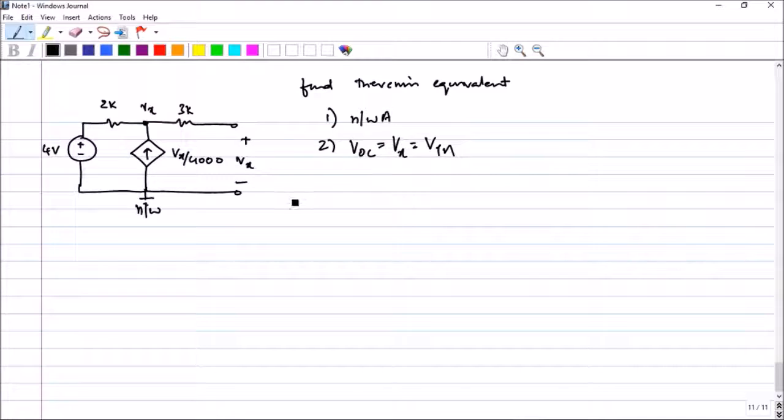Now let us go around and find the value of Vx. I can use node analysis here. So Vx minus 4 divided by 2. Now I always put 2 because this was in milliamperes, but now this is not in milliamperes. They have not specified it as milliampere, which means it might be an ampere value. Therefore, I have to put the total value. I have to convert it into the proper SI system. So don't make this mistake.